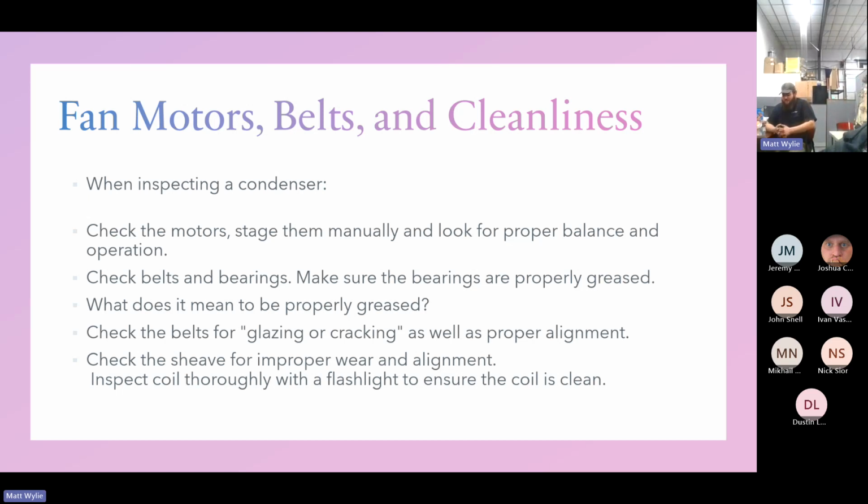So that one, Derek makes a good point. On those, like water cooled condensers on an ice machine, or a water source heat pump, check your inlet temperature of the water. Make sure it's not on the same water line teed off to your ice machine.